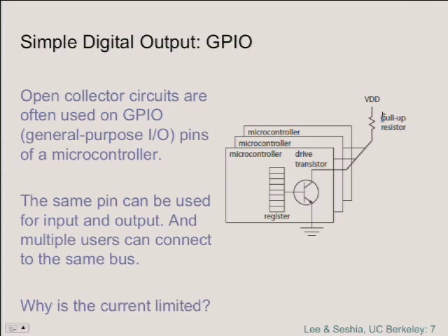And you will get some current flowing through this transistor, but this resistor is designed so that the current is totally manageable by these devices. If you're the only device that is asserting that the voltage is 0, then you've effectively conveyed information on the bus. However, there might be multiple devices asserting that the bus is 0, in which case the bus line will go to 0 and everyone will see 0, and you have to somehow disambiguate which one is which. Okay?